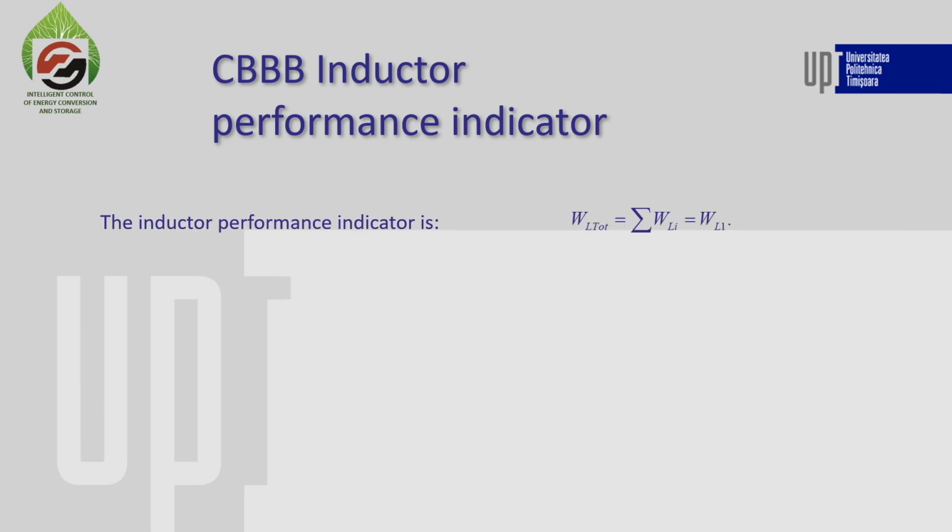Because it is insufficient to compare a converter by the number of inductors or by the current and the inductance value just alone, we use another performance indicator, which is the total energy stored in all the inductors for the converter operating at the rated parameters.